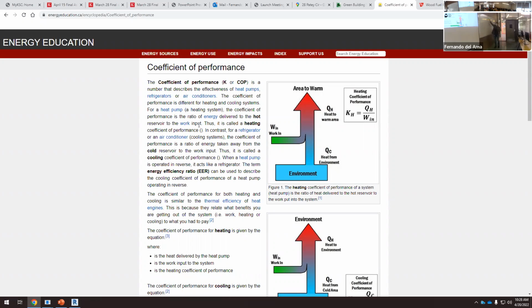Usually this is not 40,000. This is 41,285. So there is not a commercial machine with 41,285 watts. Okay, so what's the next? 45,000. Okay, 50. Okay, 100. I wouldn't do that because 100 would be too much. But something between 40 and 50 will work. So with this, I select the heat pump that meets the maximum power that I need, the peak heating load, and then I need the COP. So imagine that the COP is 4.